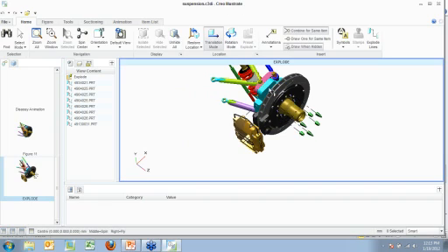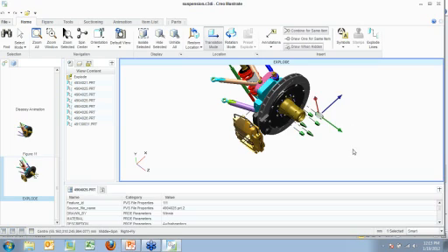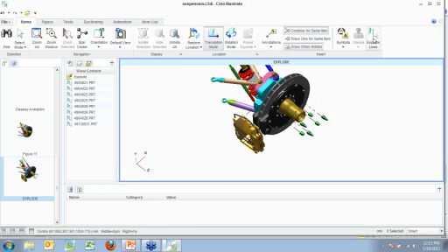So I can select translation mode or rotation mode. Go in, we'll select this little lug nut here. I can drag it. You can see that the explode line dynamically updates when I move the component, just like it would in Creo Parametric. My explode line tool is up here. And that's as simple as you select it and snap between a couple of points.